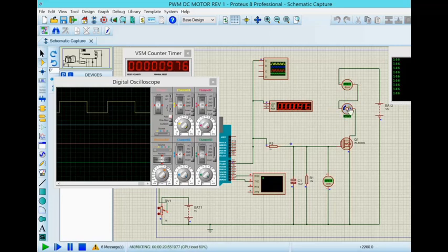Remember, the coil has a set 12 ohms coil plus whatever resistance you have here. That makes sense for this value. Looks like that's it. 81. Maybe if I get this to the maximum, let's jump here. You see, the amp is still in the same place, never changes. So that means the MOSFET is well fired.